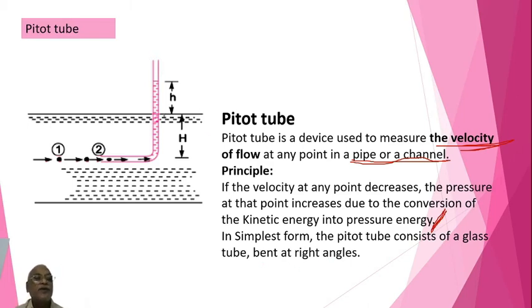So whatever pink tube is there, which is bent, is held with its face as if the flow is entering into that. If you hold it the other way around, nothing happens, right? So rather you will not be able to get anything. This tube has to be kept open so that the entry of the flow occurs, right?